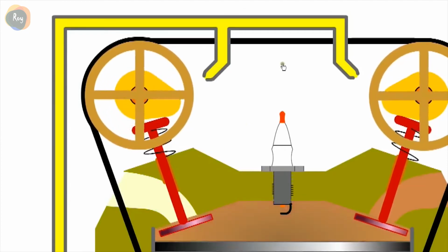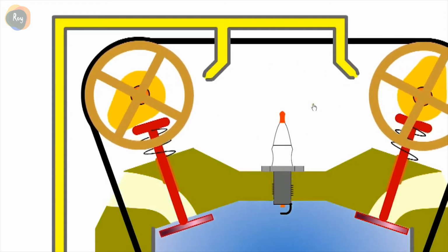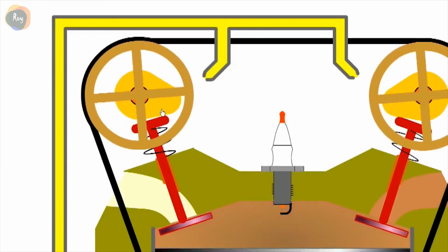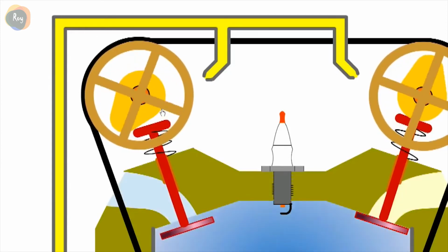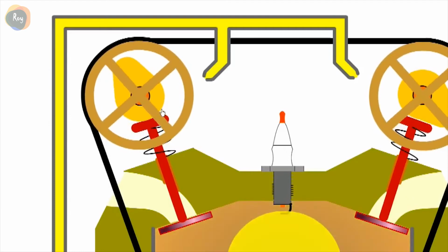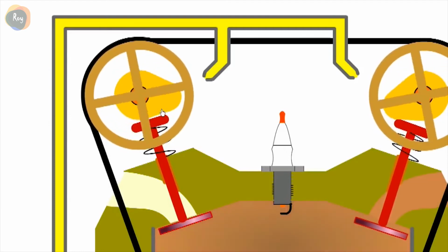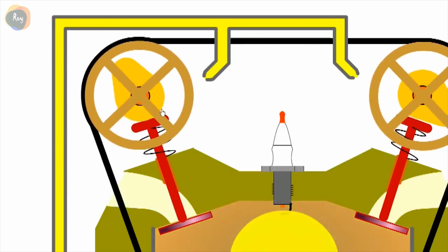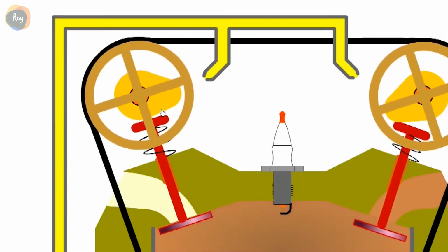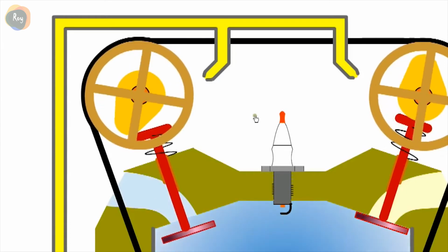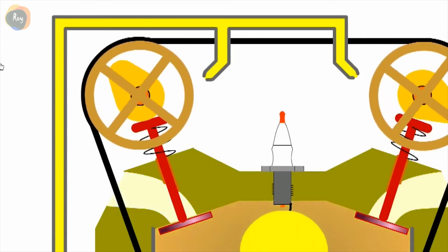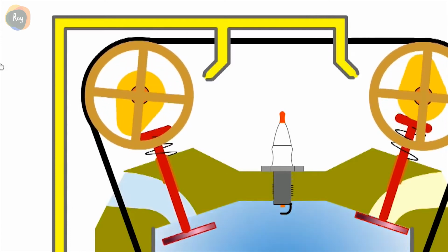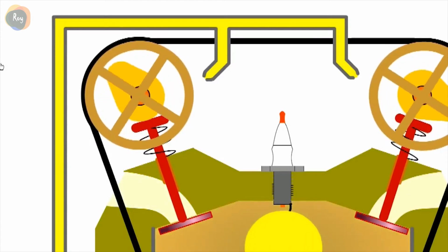Ideally, there should be an oil mist in the crankcase and around the camshafts. However, we do not want a build-up of combustible gases from blow-by. In the past, the ventilation was vented to atmosphere, but this was considered a source of hydrocarbon emissions. The PCV positive crankcase ventilation system routes combustible gases to the intake manifold where they are burned, thus reducing emissions and preventing overpressurizing of the engine.